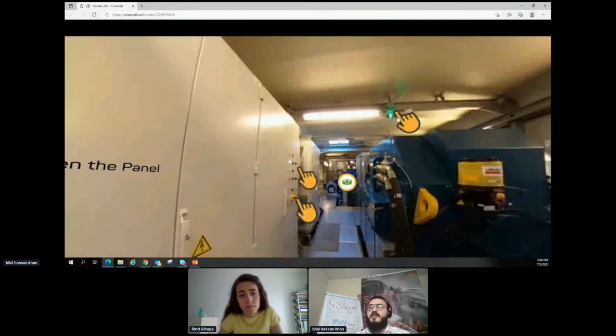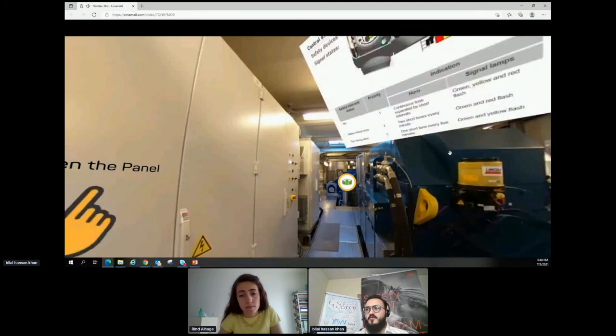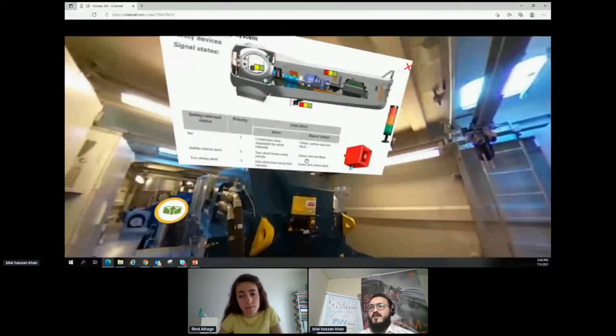Also, we have some indication lights in the nacelle in the Delta 3 turbines. These lights also give us information with the help of a hooter and the condition of the lights. For example, if we have a fire inside the turbine, then the hooter starts to make noise, and the green, yellow, and red lights start to flash together. In the other condition, if you have any safety critical error, it will not horn all the time. Only 2 short tones every minute, and only the green and red light will blink.